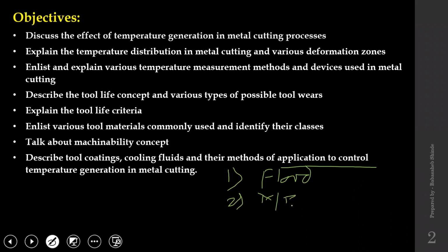Second, mist cooling. So create a mist of that lubricating fluid and provide it in the form of spray. So minimum fluid needs to be provided. You can have better effect also compared to flooding or flood cooling, because here the amount of fluid that has to be provided is very large, and using that large amount of cutting fluid, there might be difficulties in disposal of that cutting fluid also. You cannot simply throw that cutting fluid open in the atmosphere, right?